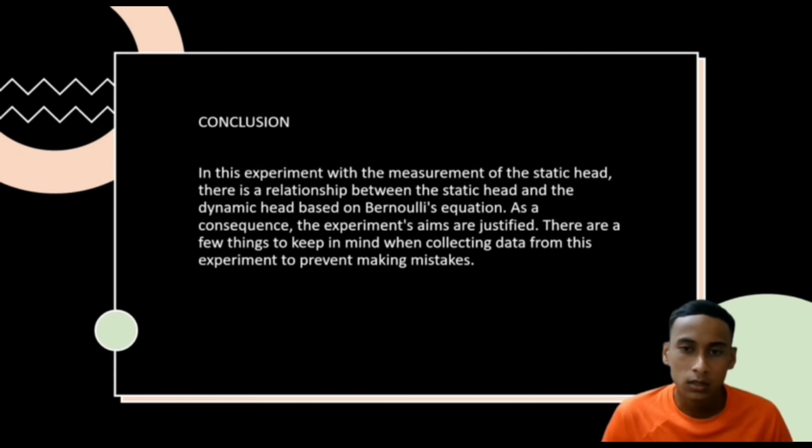In fluid dynamics, the Bernoulli principle states that an increase in the speed of fluid occurs simultaneously with a decrease in static pressure or a decrease in the fluid's potential energy. So, in this experiment, with the measurement of the static head, there is a relationship between the static head and the dynamic head based on the Bernoulli equation. As a consequence, the experiment aims are justified.